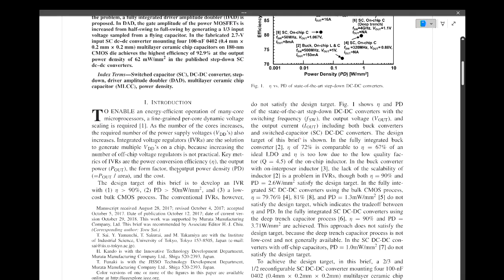Like I was thinking that during the first one, it works even when it's not settled, right? Yeah, but that's not normally how you use them, because the normal assumption in a switched capacitor circuit is that you wait until it's completely settled every time. It's assumed that the clock frequency is high. So you assume that the clock period is long enough so that the RC time constant in charging and discharging the capacitor, you can ignore that.